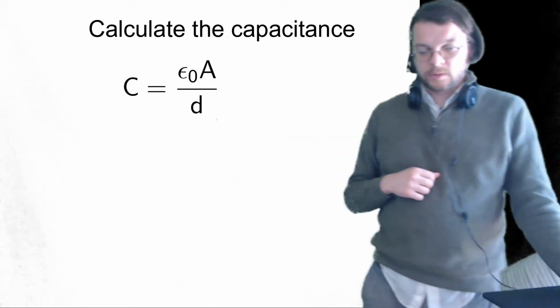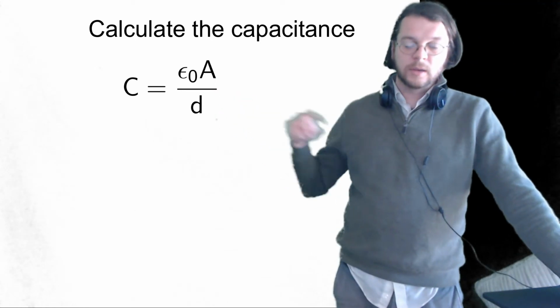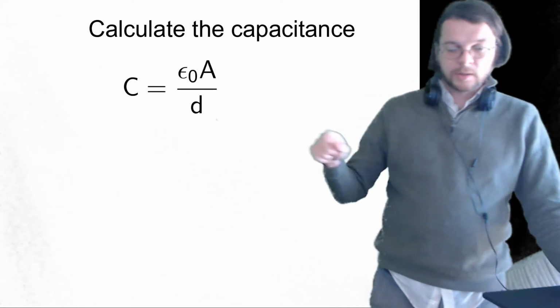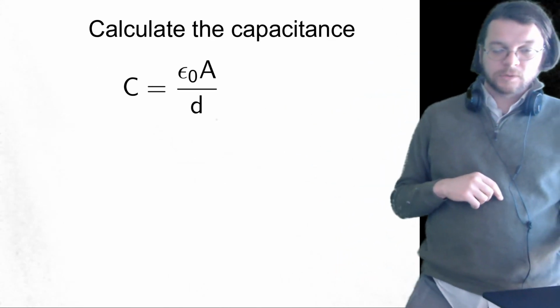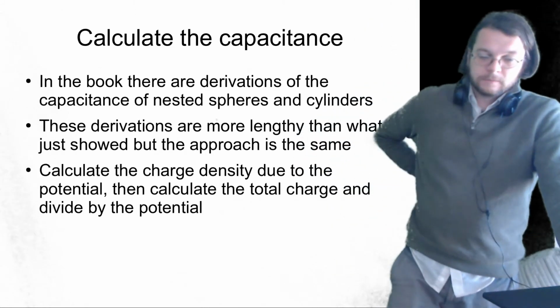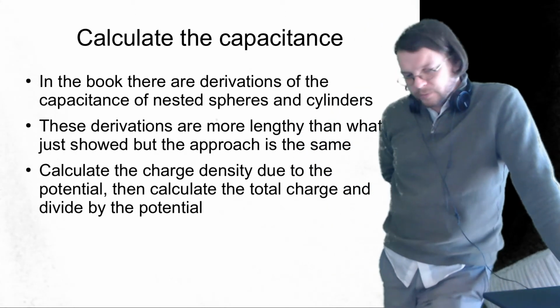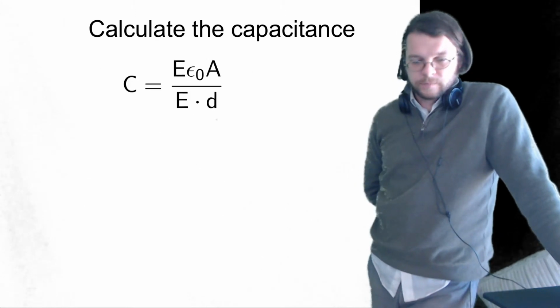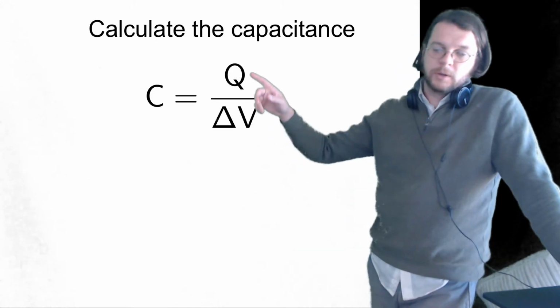So that's our formula for what the capacitance is. And this sort of thing you could use with that keyboard key to try to figure out how much the voltage would change if it was pressed down, because it would change d here, right? All right. Now there's a lot of questions in the book that are similar in spirit to what I just did,